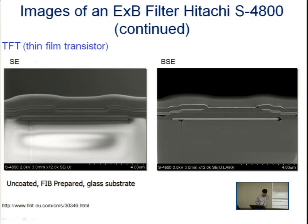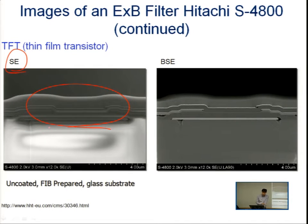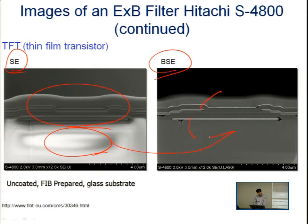And then this is again the secondary electron detector, which does not show any differences between the elements, and it even has this kind of charging effect. But using the backscattered electrons, we can clearly see different elements based on the different structures, and it also does not have those charging effects.